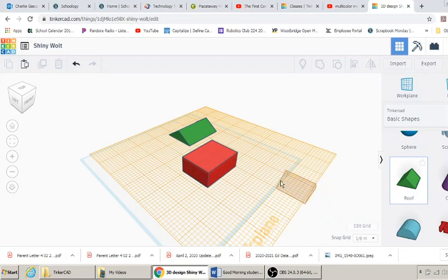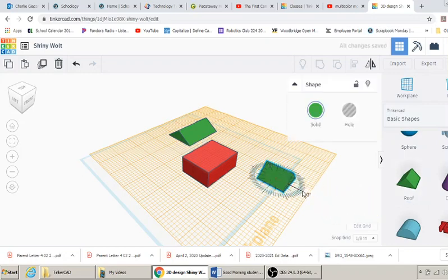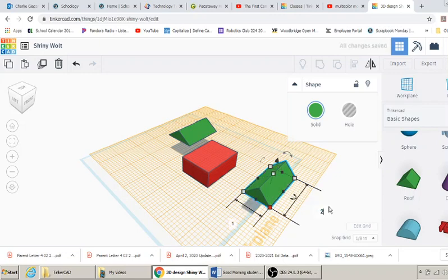I grab the roof tool again. I'm going to rotate it around into position now so you can visualize it better. And I'm just going to extend its proportions a little bit. Instead of being 2 inches long, I'm going to add 1/8 of an inch for the eaves overhang, so 1/8 of an inch on each side would be 2.25 inches long. The same with our depth of the house. Instead of 1.5 inches, I'm going to add 1/4 inch to make it 1.75.